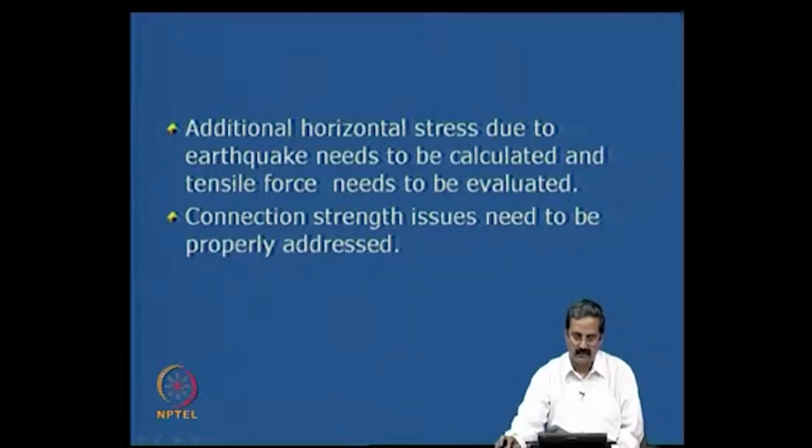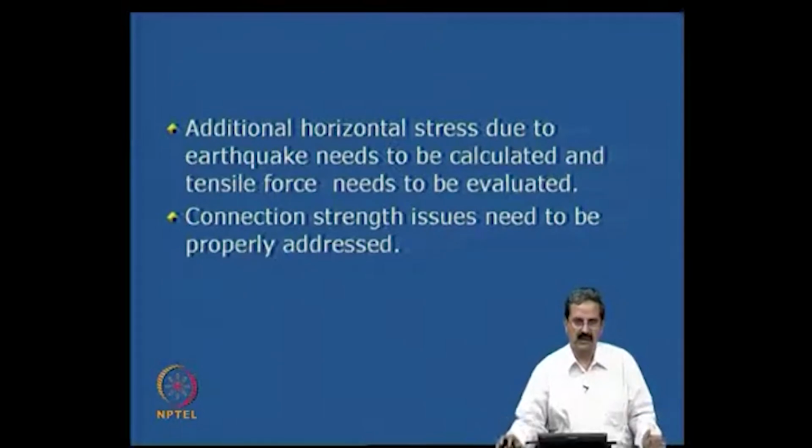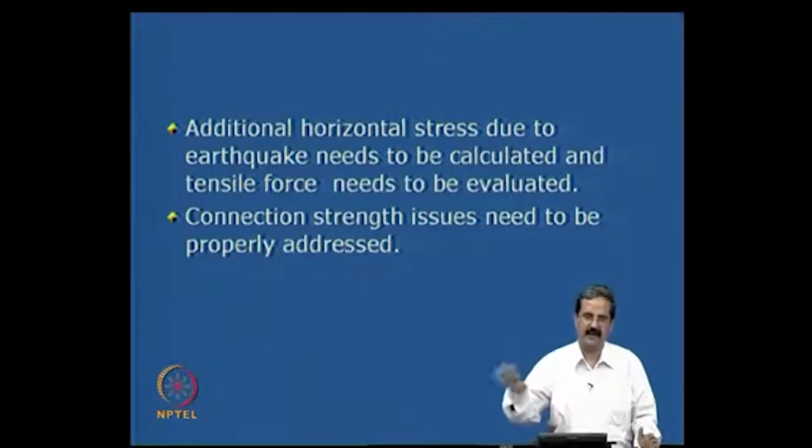Then connection strength. A very important point is that when an earthquake comes, or even in the simple case, we connect the reinforcement to the facing using some connections. If the connections are not good, there is a possibility that it can go very badly. All specifications of backfill, compaction, everything is perfect, but if the connection strength is poor,